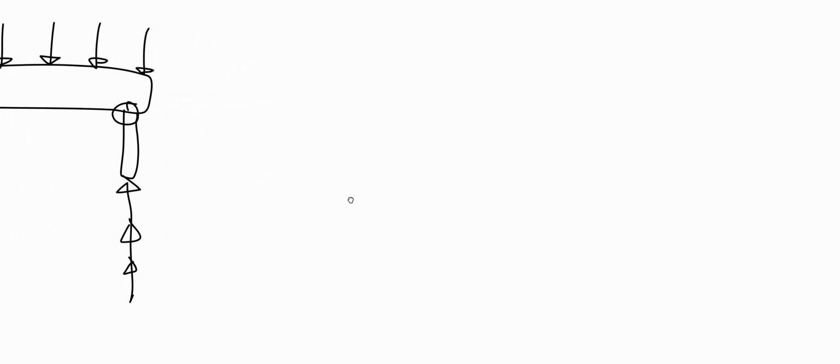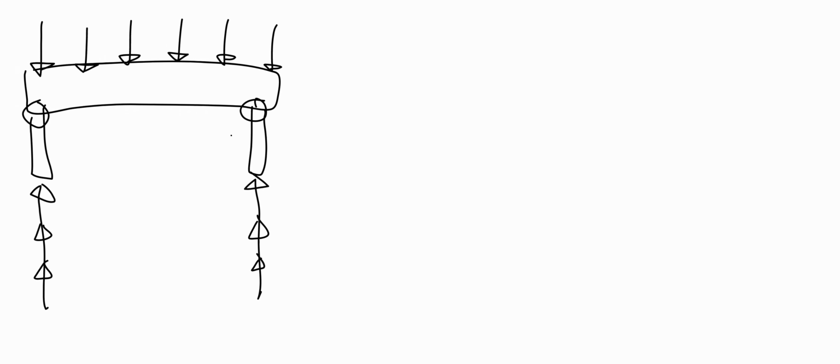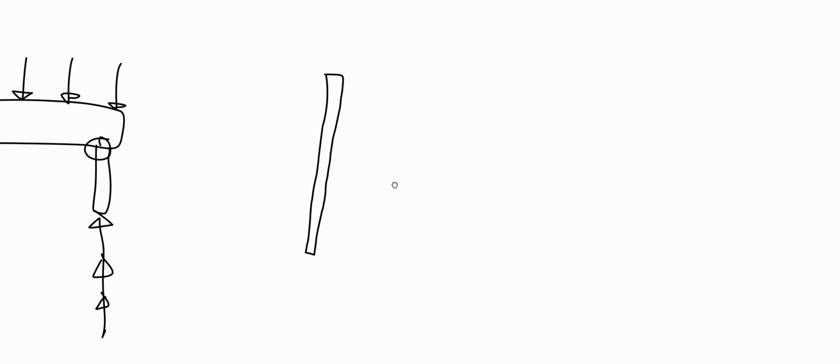Now, in this situation, where this beam is being loaded like this, there are a few different ways this beam could fail from stress, but the most likely and the most reasonable is that the cross section of the beam is experiencing compression and tension. So I'm going to take a cross section of this and draw over here. Well, it's not really a cross section, but we're just going to look closer at the center of this beam. So the center chunk of this beam, let's say we took a slice out of it like a bread loaf. It's at an angle. Pretend it's not an angle.